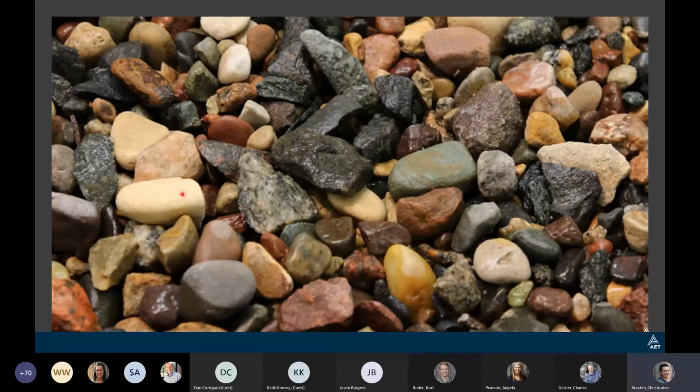So if you have a pile of rocks, a natural gravel, this is what you're looking at. And like I said, with a natural gravel, you can have up to 15 thin sections because there might be 15 different looking lithologies in there. But once you start getting more experienced at it, it gets a little bit easier to do picks. If you follow my laser pointer, pick, that's a granite. Over here, you can probably find there's a granite right there. And then you can start looking like, okay, so these granites, they're nice, they're angular, they're nice clean fractures, they look crystalline, they look hard, they look solid. You can qualify those as a good, hard, solid aggregate.